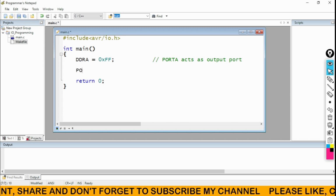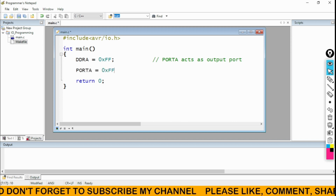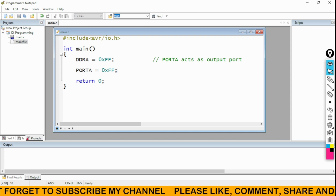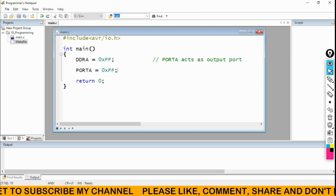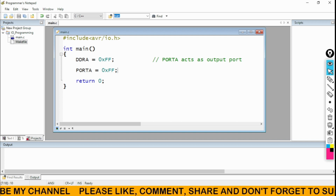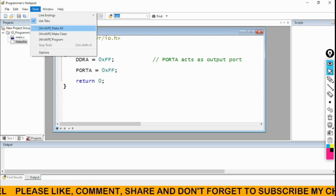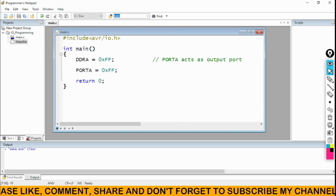Then we directly write PORTA equal to 0xFF, which means that this particular port A has the data FF. If I run this program, how do we run it? First of all we go into Tools, Make Clean.